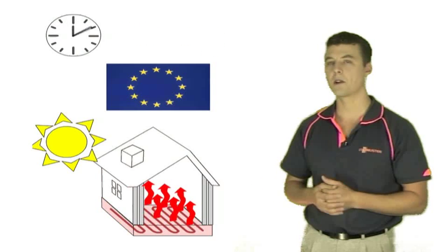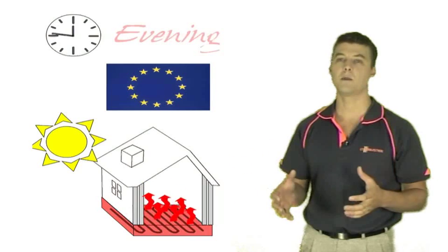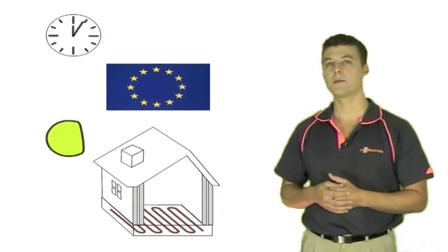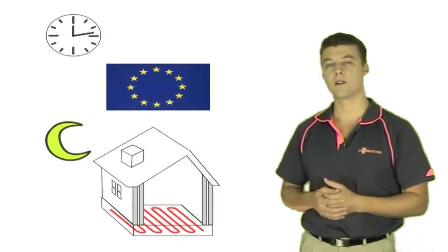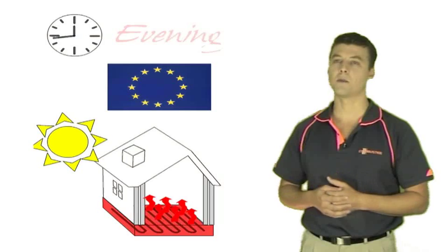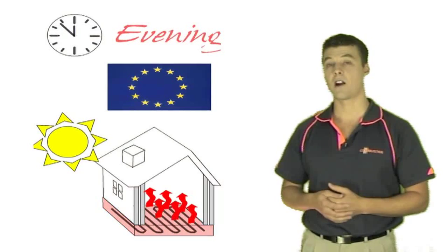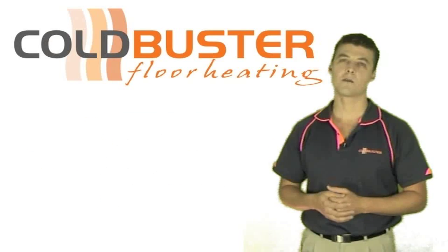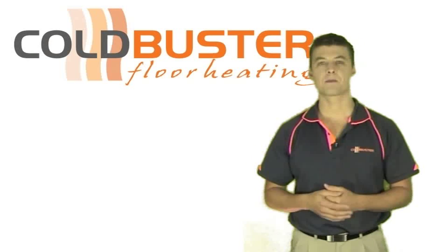Slab heating responds slowly because the entire mass of the concrete slab needs to be heated. These lengthy lag times can take up to a few days to heat the slab when first switched on at the beginning of winter. Slab heating sometimes requires a boost for a few hours in the evening when energy costs are at their highest. There are a number of reasons why in-slab heating is not energy efficient in Australia.